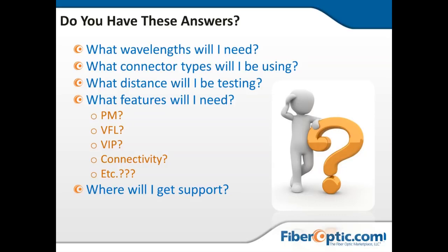So step one was the power meter. Step two became the OTDR. So they had actually a single wavelength OTDR. That's why they call it a break locator, not an OTDR, because it was really using one wavelength, and really we like to consider two wavelengths whenever using OTDR so that we can detect macro bends and other things in there. But for a simple troubleshooting process, we shot out a 1625 nanometer wavelength over that fiber to see if there was a break down the span, some distance.